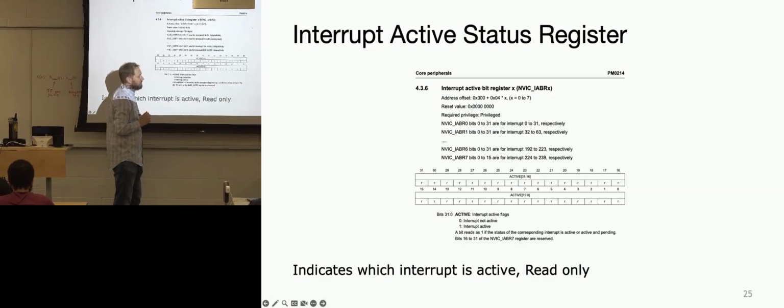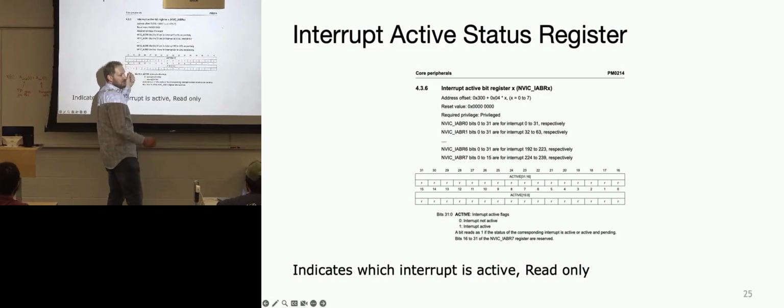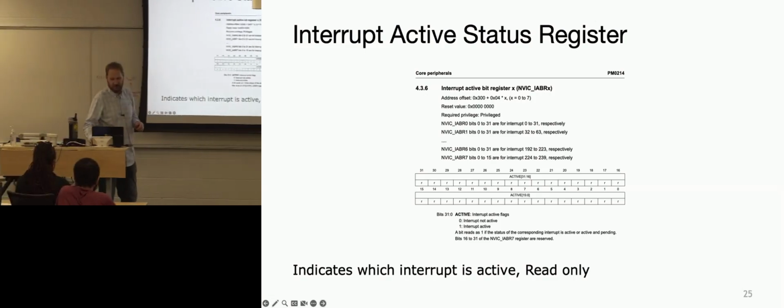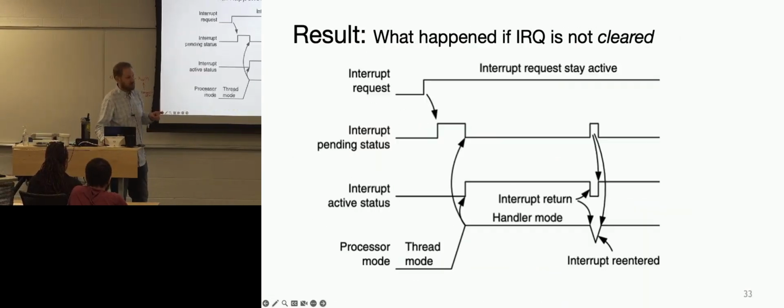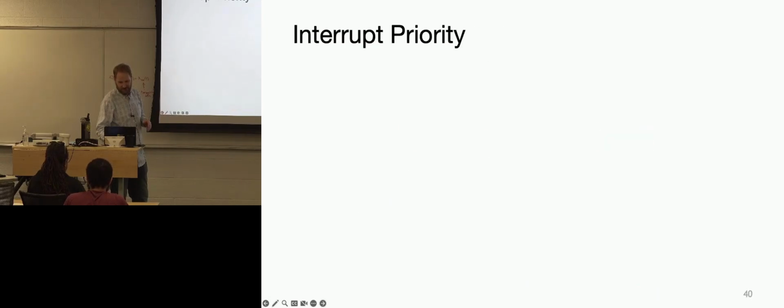Okay. Will that get pushed to the stack on the interrupt? Is that part of the stack? No, it doesn't need to get pushed because this doesn't actually hold real state information that you would need if you're stacking and unstacking, because that's held on the stack. Right, but knowing which active to go back to if you're in deeply nested interrupts, like I was asking before. But remember, what's the structure that holds that information? Well, I kind of thought it would be that register. Nope, it literally is the stack.